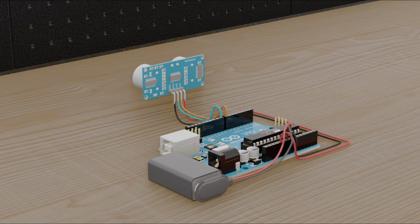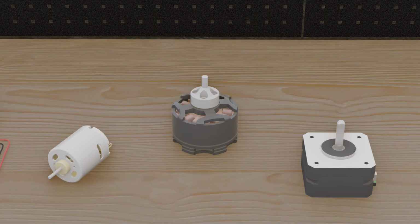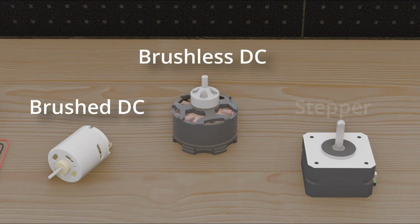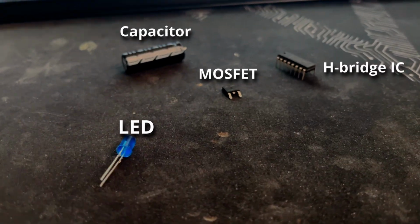So the Arduino can know what's going on around it with sensors. Now we want to do stuff with that information. If we want to move around in response to that information, we can use actuators. Actuators are things that can cause movement, like motors and pistons. They can connect to some wheels to make a robot move forward, or to an arm to move something else. There are multiple types of motors, like brushed DC motors, brushless DC motors, stepper motors, and many more. However, the main concept of being able to move stuff with them, especially after getting information from a sensor, still applies.